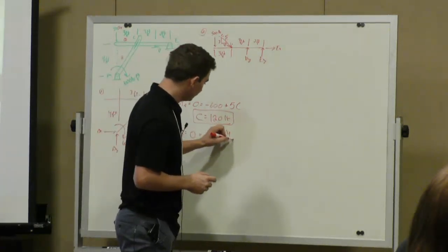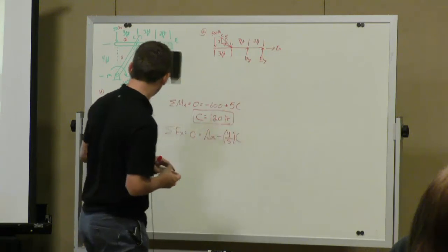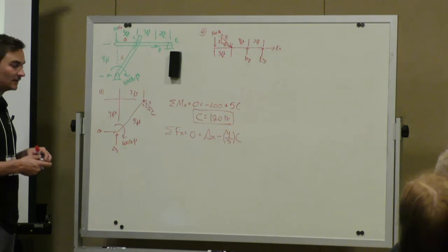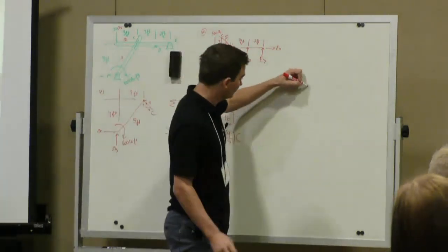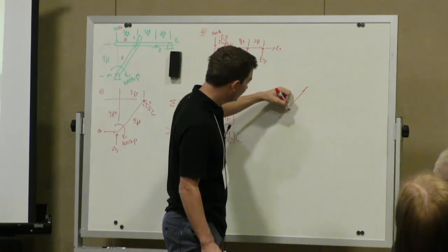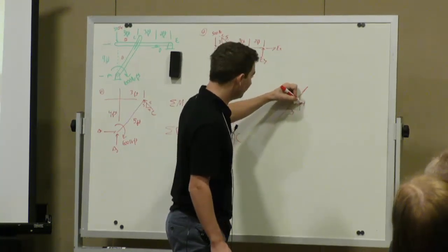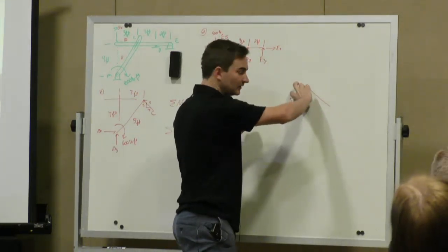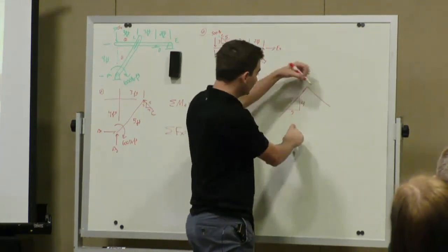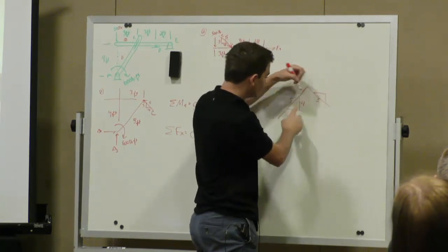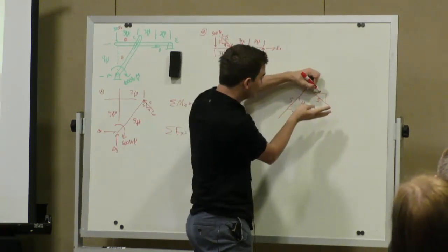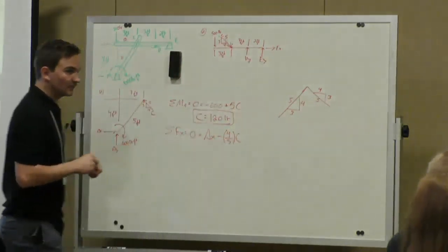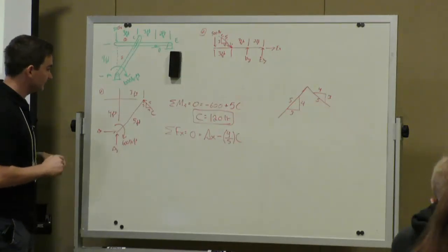On that triangle, how come the 4 is on the bottom? Like, how come you set it up like that? Because it's perpendicular to the other one, so its legs are touching. Our original one, the one about our member, is a 3, 4, 5. So now if you want it perpendicular, you're essentially rotating these two. So this goes on the top and this goes on the bottom. If we rotate that triangle, the hypotenuse is still 5. This gets rotated 90 degrees, so that goes to the top. This gets rotated 90 degrees. That's 3. That's one way to look at it. Thank you. Yep, good question.